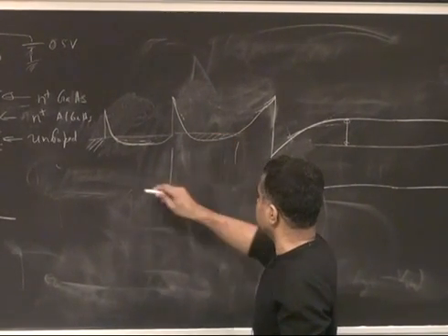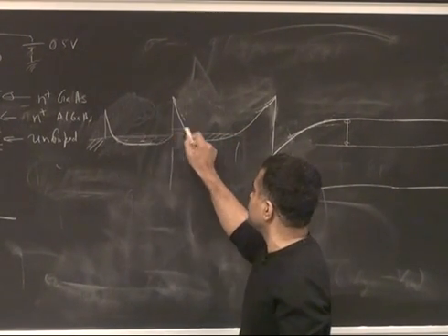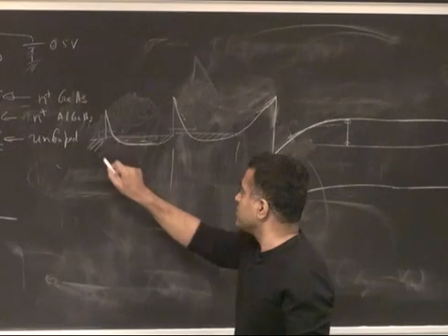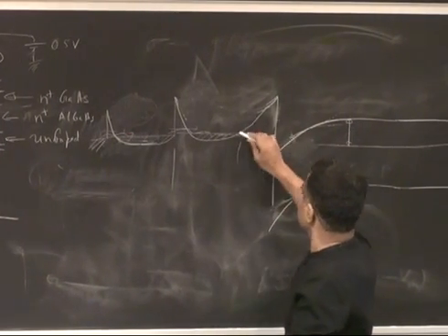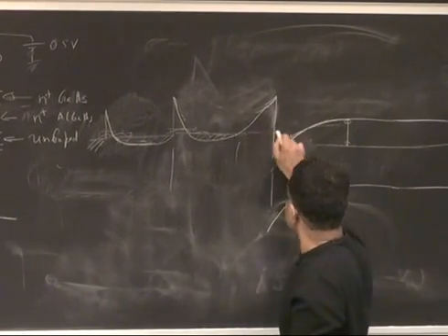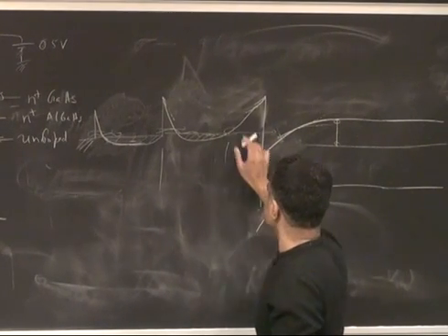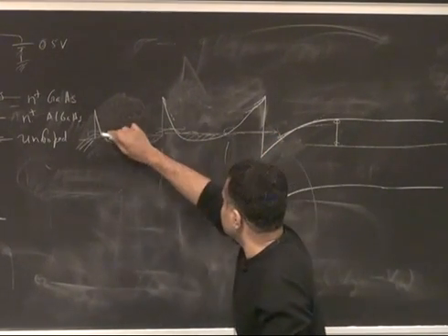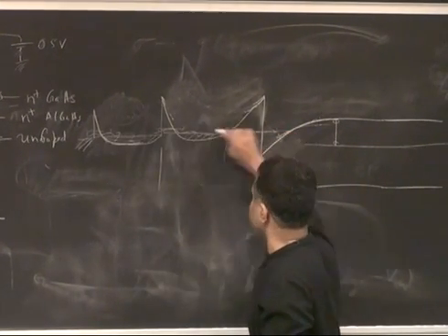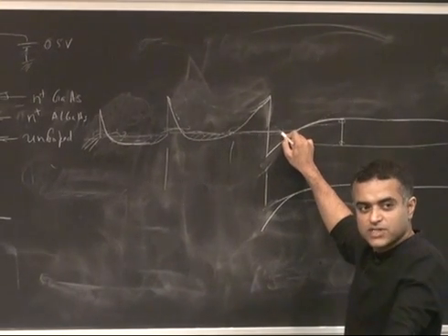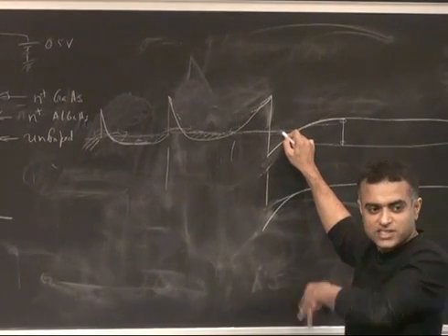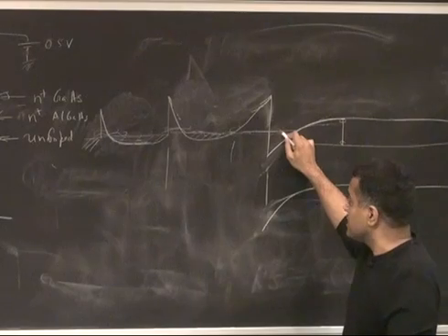So you have a pool of electrons here, a pool of electrons here, and a thin barrier for tunneling, so electrons can tunnel through. And if you look at this barrier, it also becomes very thin by the time you reach here. So it's a rather difficult process to connect to the electron gas with a low resistance, but this gives you much lower resistance than if they did it by other techniques.